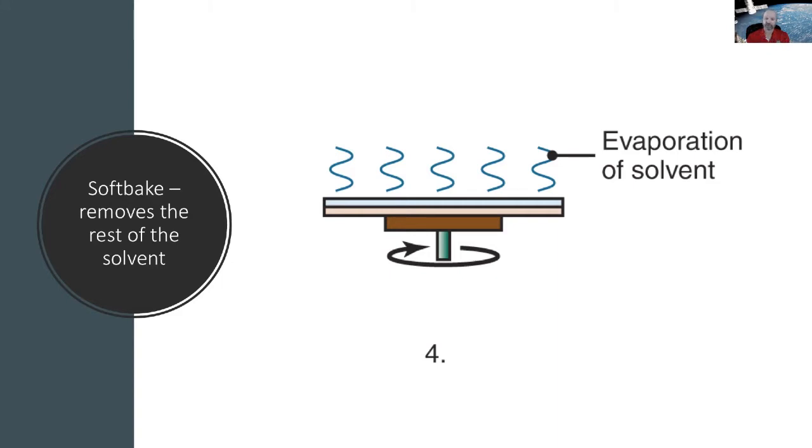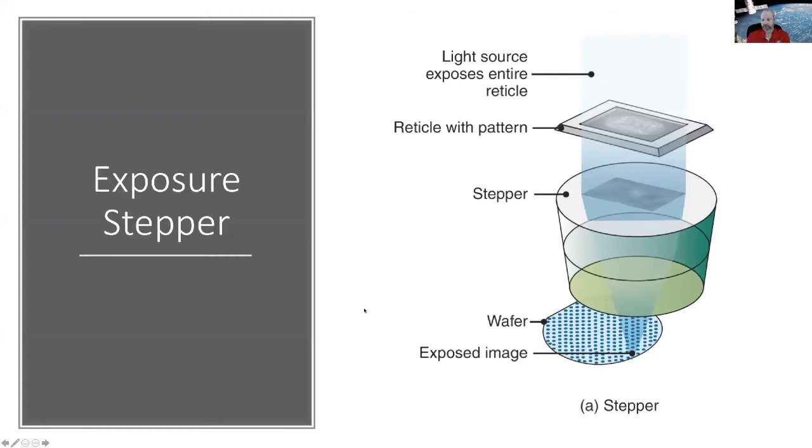So we had a big project at TI to reduce the amount of photoresist dispensed on the wafers. And we actually went from 2 milliliters down to 0.8 milliliters, which was a huge savings. I think it was on the order of $2 million a year in photoresist, just for one type of photoresist that we were using. So that's an example of some of the work you do as a process engineer, working for a place like Texas Instruments or IM Flash.